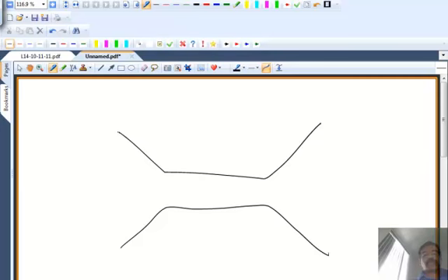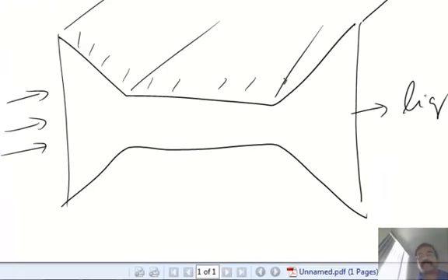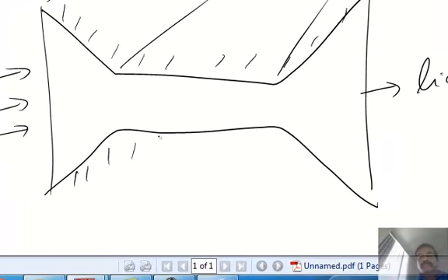Okay. And perpendicular to the board, it's infinitely long. It's a channel. So the liquid is coming in and liquid is going out. And these are all walls. And I want to obtain the velocity field and the pressure field by solving the Navier-Stokes equation for this geometry.